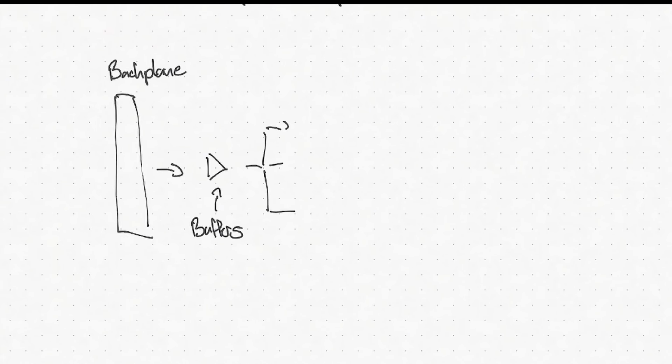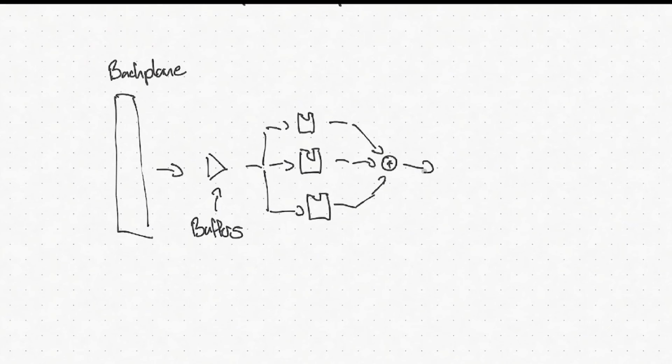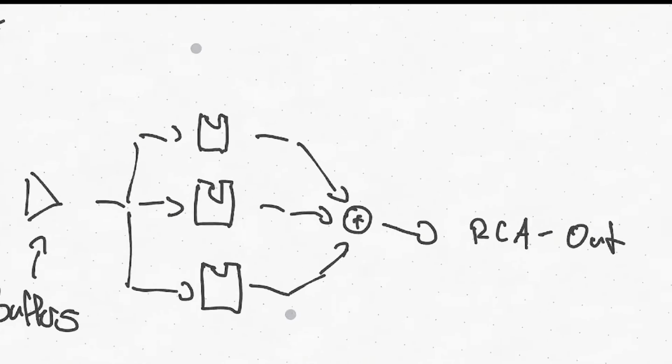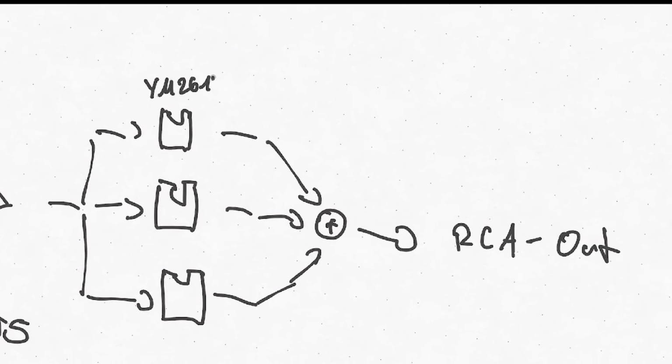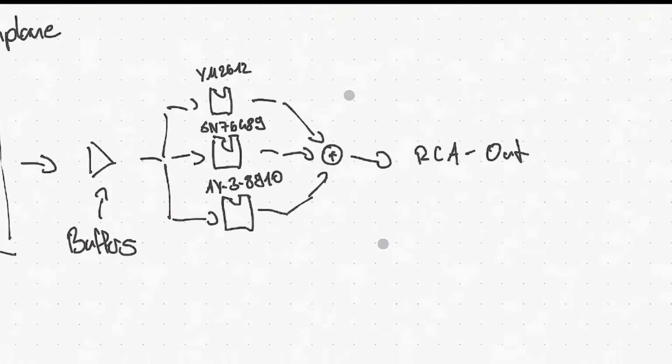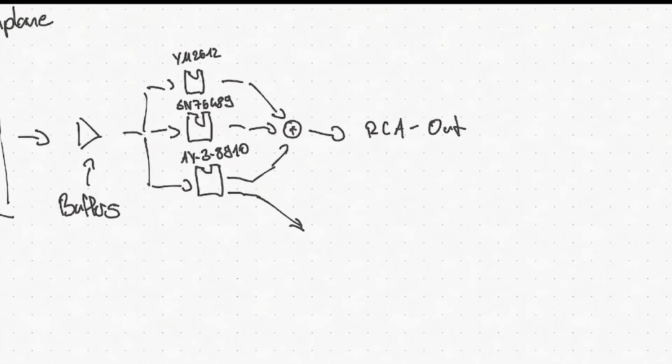Right here you can see a small block diagram that I tried to draw. On the left you can see the backplane connector, which connects to the Z80 bus, which then goes through some buffers to put a little less stress on the CPU bus, which then goes to the 3 sound generators and to the SIO IC. The 3 sound generators are mixed together into a stereo signal, which is then outputted through 2 RCA jacks.